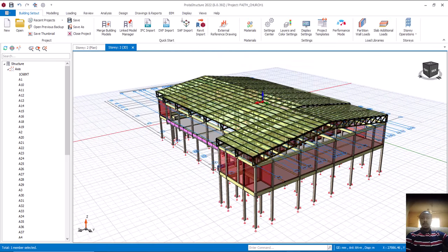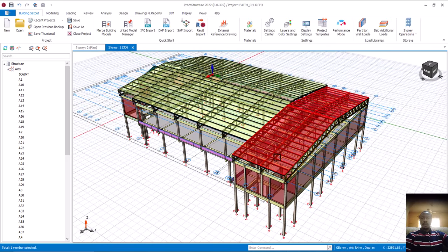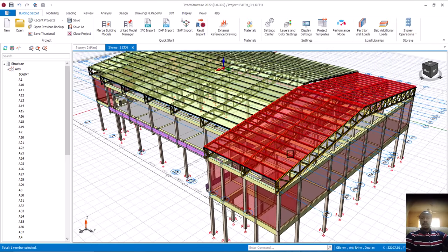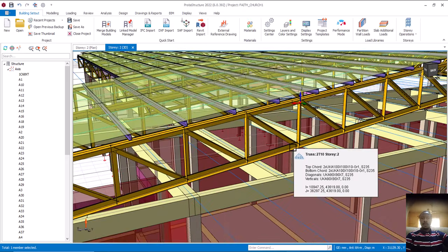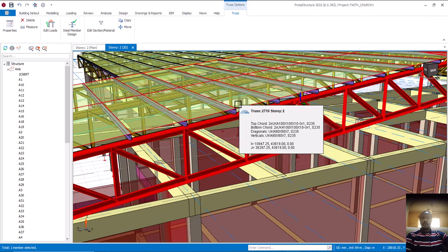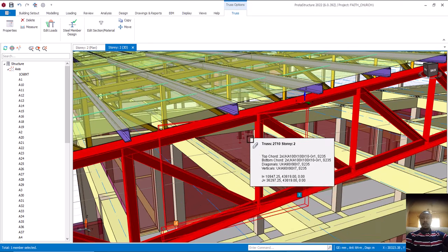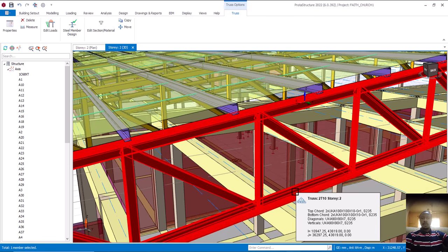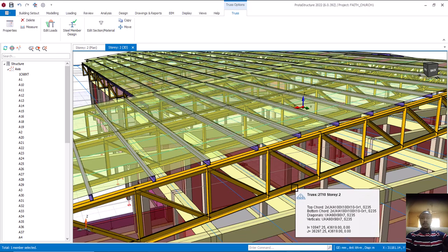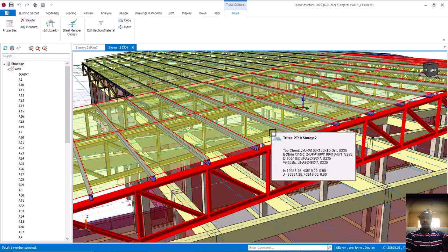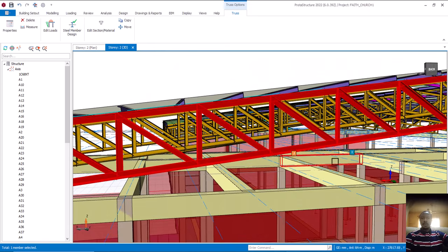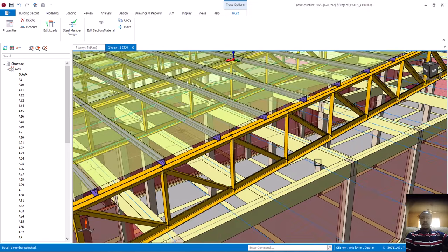This one now we have loaded it. So this is how you go about the calculation of your roofing sheet. Don't forget that, based on ProtaStructure, the self weight of your members has been calculated by the software. All these purlins, top chord, diagonals and the bottom chord have all been calculated by the software. So you don't need to bother yourself about that. What you are calculating is your roofing sheet load and all the ceilings they are going to be using here, which I've already explained. Is that okay? All right, that is fine.